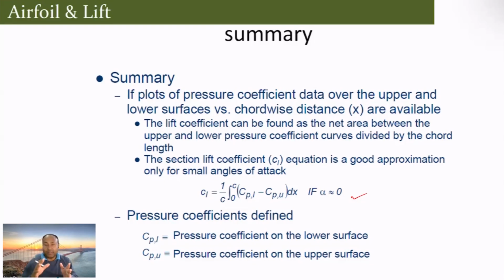Obviously, drag increases. So this is the same concept which needs to be used while designing the rotor blade also, because the lift causes it to rotate, and the rotation is the main component here where you are converting your wind energy. The wind flow hitting the rotor blade, because of its airfoil sections at different planes, makes it rotate. That rotation goes to the low speed shaft, to the high speed shaft, to the generator and produces electricity.